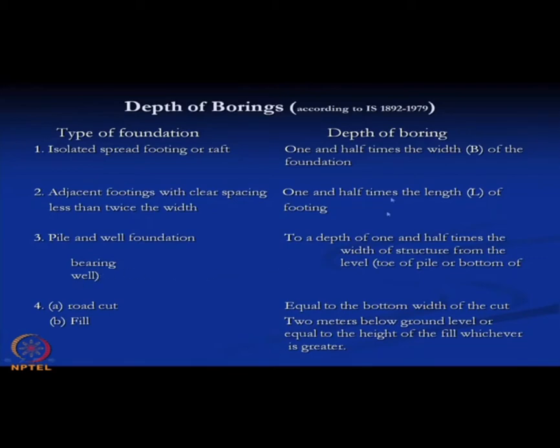So, that means from the bearing level. So, if it is a pile or well foundation, to a depth of 1.5 times the width of the structure from the bearing level, that is the toe of pile or bottom of the well.